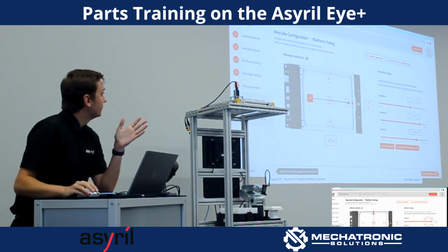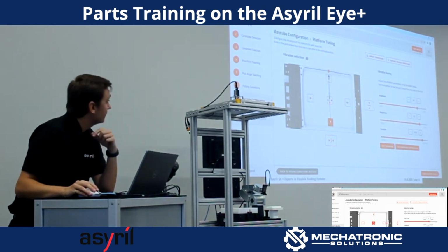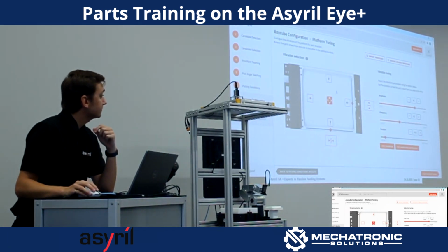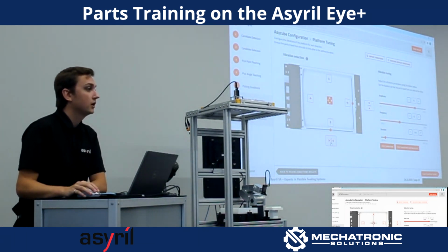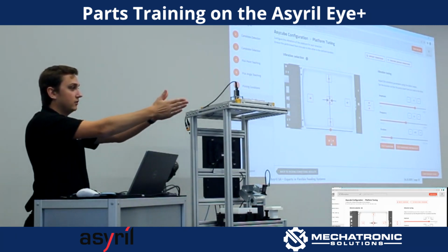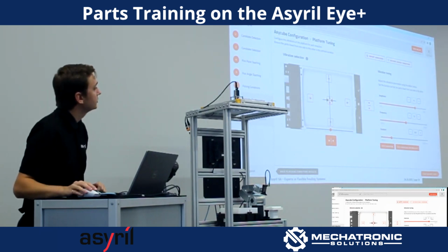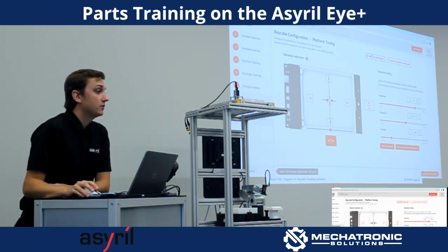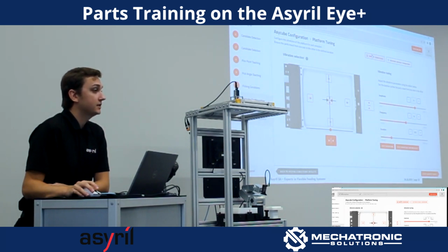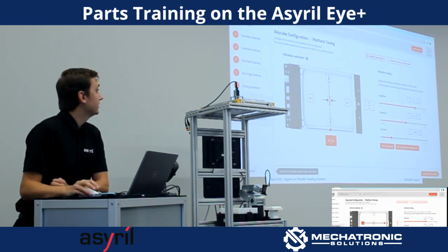And so you would go through and tune all of these features here. This is all of the different directions and a flip. And then these are our cross centering and long centering features. So if you want to move parts to the middle like that in a flat way or like that, that's what these two functions are for. You can also import vibrations from a previous recipe. If there are parts that behave very similarly on the ASYcube, you can import those vibrations directly from a different recipe and simplify this step as well.